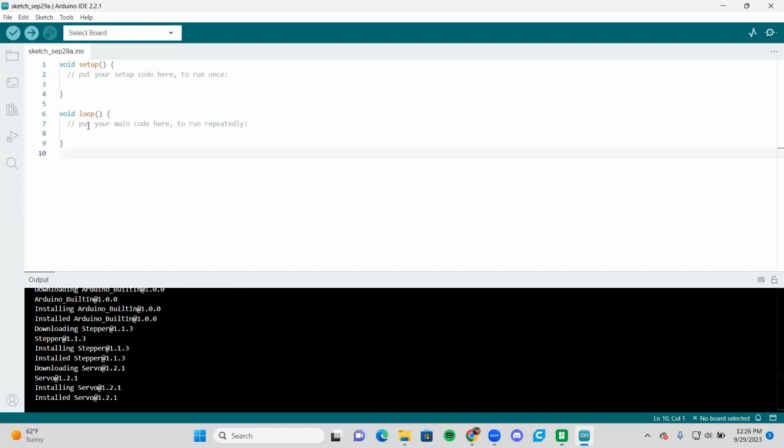As I said, microcontrollers are really good at running instructions over and over again, and that's where you put it, in this loop function. Other than that, you have this check button. Arduino is a compiled language, so you have to compile and verify it before you upload it to your board. When you want to upload your code, you will have to connect your board with that red wire. If you run through the SparkFun Inventor's Kit manual, it will tell you all of this, but it is a little outdated, so I was just showing you how to get this downloaded.